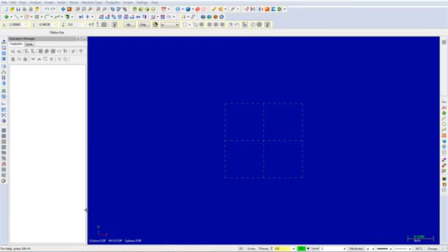The first thing we will do is create rectangles. In this step, you will create rectangles using the Rectangular Shapes Option command. In this command, you can create a rectangle using a base point or two-point method. You can set a corner fillet radius, rotation angle, and general shape. Choose Create Rectangular Shapes.